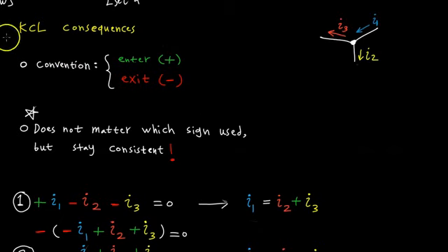But it's important to assign directionality to those currents, because obviously at a given node, currents don't only enter or only leave, they can enter or leave. And since we're talking about algebra, one way to distinguish opposites is to assign a plus and a minus sign. So you could make up a convention, and that's what's usually used, which says that if a current is entering a node, it obtains a plus sign in the algebraic sum.